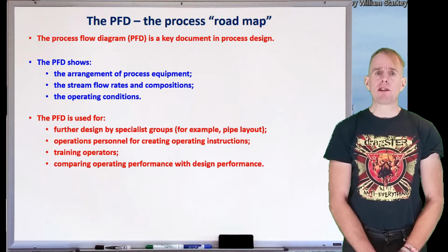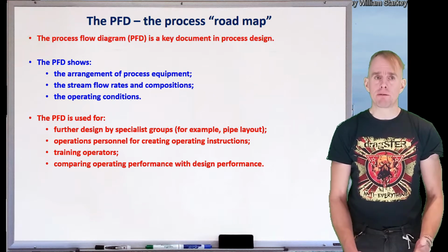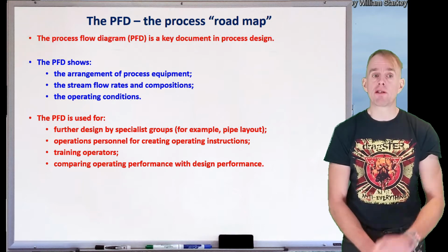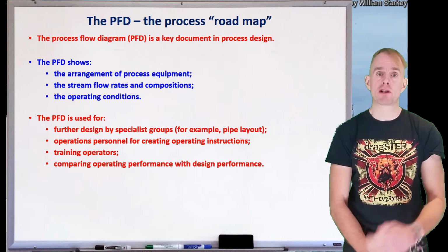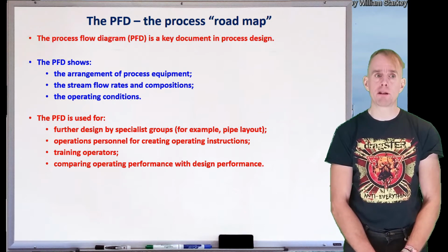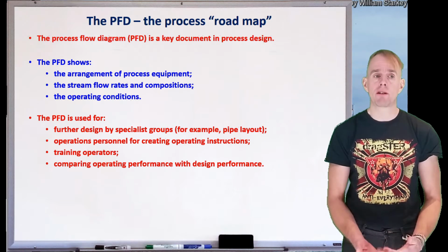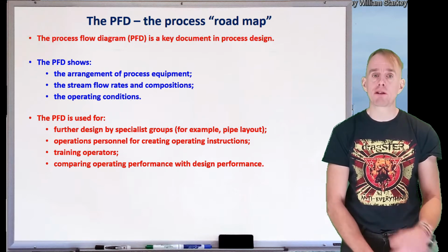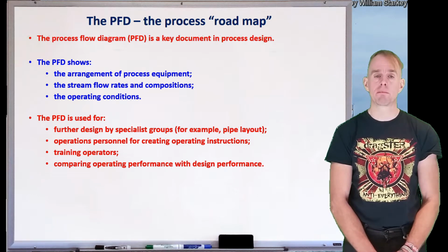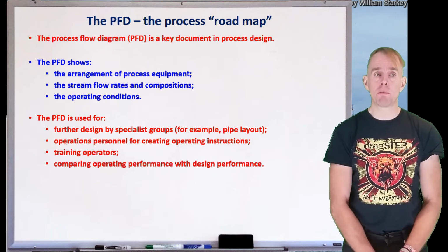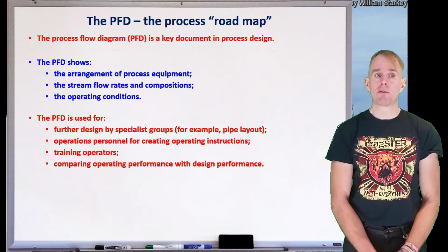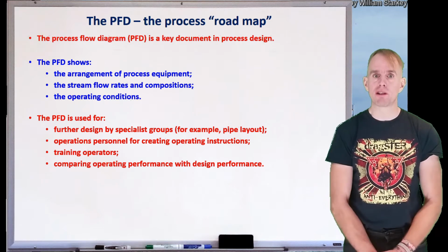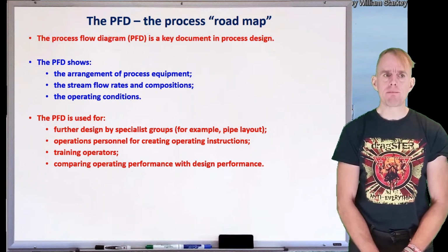The PFD is an essential document. It is used by many different disciplines. It can be used by the design team to further evolve the design and to be passed on to specialist design groups, for example piping layout groups. It can be used as a training document, for example during operations, for training operations personnel and for creating operating instructions for the plant. Furthermore, it can be used for training operators, and it can also be used for comparing operating performance with design performance. Sometimes these two things can be rather different.